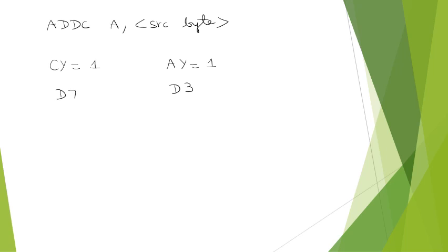For unsigned integer addition, the carry flag indicates that overflow has occurred. The overflow flag is set when there is a carry out from the D6 bit but not the D7 bit, or there is a carry out from the D7 bit but not the D6 bit, else the overflow flag is cleared. And while adding signed integers, the overflow flag indicates that a negative number is produced as the sum of two positive numbers, or a positive number is produced as the sum of two negative numbers.